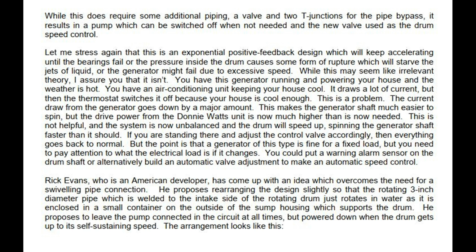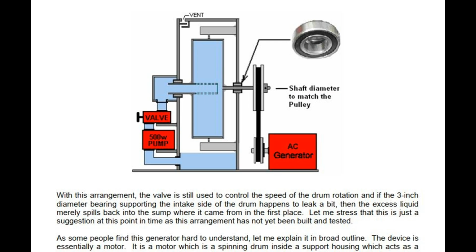He proposes to leave the pump connected in the circuit at all times, but powered down when the drum gets up to its self-sustaining speed. The arrangement looks like this. With this arrangement, the valve is still used to control the speed of the drum rotation, and if the 3-inch diameter bearing supporting the intake side of the drum happens to leak a bit, then the excess liquid merely spills back into the sump where it came from in the first place.